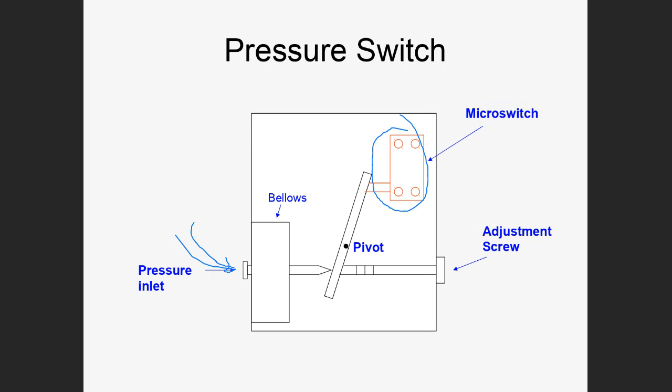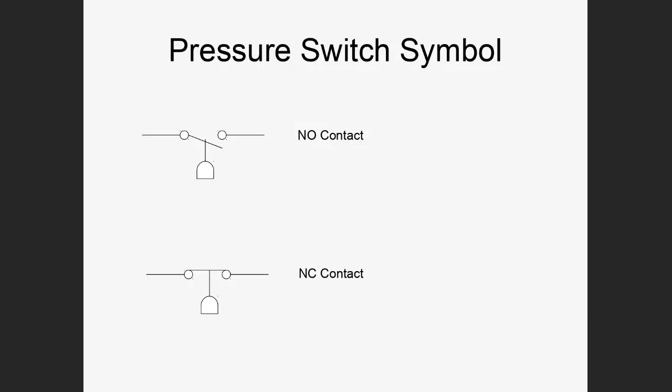So you may be familiar with the pressure mat, or when you roll up to a stoplight on some intersections, they actually have pressure switches made into the blacktop. They can sense, or maybe going into a garage, if they don't have an optical sensor, they have pressure sensors in the ground, and these are all electronic type sensors. But those are other field devices you can have, and you can connect those to a PLC.